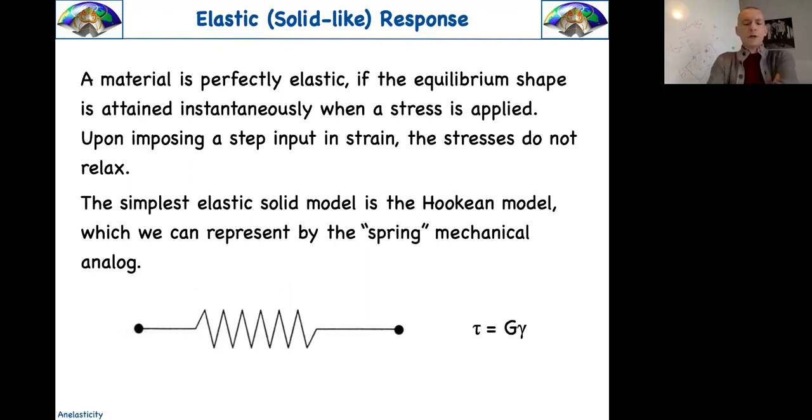Let's imagine now to consider two experiments to be applied to this system. The first one is, we apply a stress and we study the strain. So we take it in equilibrium, we apply a stress, and we study the strain. You can answer it immediately, and it's responding immediately. By the way, we will call this a creep experiment. New word, new name for something that is very simple for us. On the other hand, we can apply a deformation and study how the stress is evolving. That is called stress relaxation.